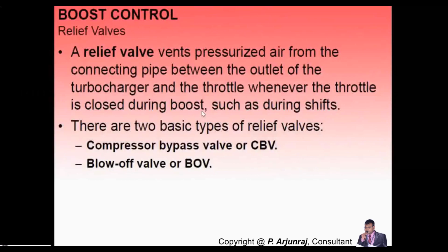Valve opening, in the sense, it will open when the boost pressure comes to the normal or required boost pressure. Okay, and it should not always be in closed condition either. When it is always in closed condition, what happens is you will not get enough boost pressure. So you need to be very careful while selecting the valves, and there is a possibility the valve can get stuck. When the valve gets stuck, there is a possibility the boost pressure will get stuck, and again this will also affect your efficiency.